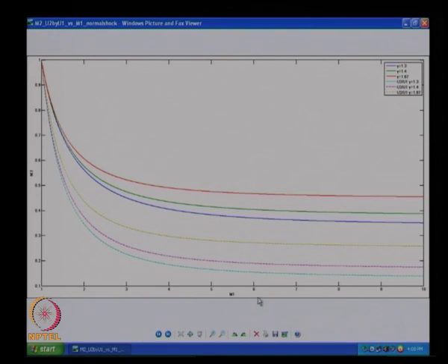If I go above Mach 5 or so, the downstream Mach number across a normal shock is almost the same value always, irrespective of what my incoming Mach number is. This is the regime we call hypersonics, where things will go almost the same.